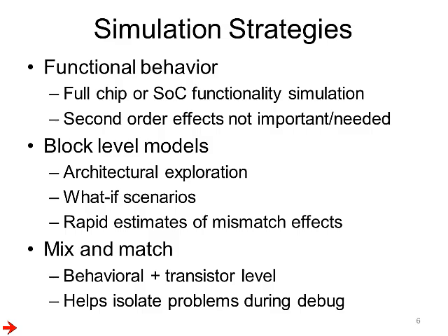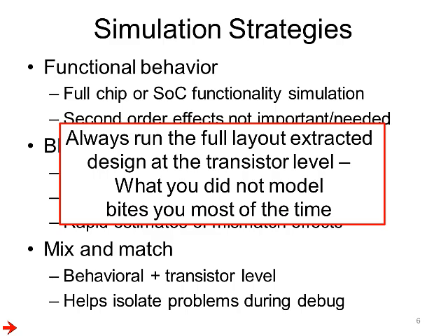Block level models enable architectural exploration, what if scenarios, rapid estimation of mismatch effects, and a mix and match approach combining behavioral and transistor level simulations help isolate problems, especially during debug. However, I would always strongly recommend to run the full layout extracted design at the transistor level, because what you did not model is what bites you most of the time.